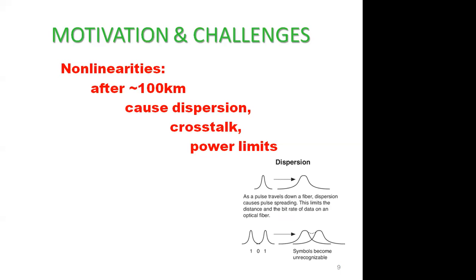What is non-linearity? There are a few parameters that come into the picture, such as cross phase modulation and four-wave mixing. Probably you will be studying that in the third or fourth or fifth units. So these are the non-linearities that we don't want. And then it crosses into dispersion. Dispersion basically gets into crosstalk.